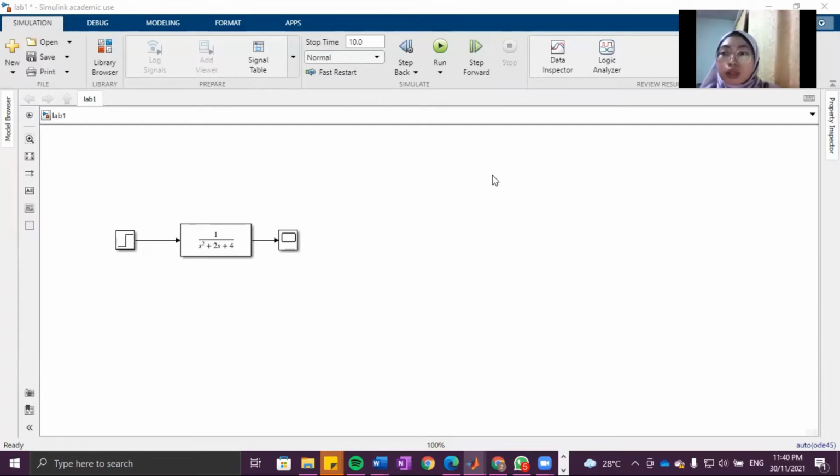So how is the data acquired? We can design a simple transfer function and get the data. The block diagram needed for this part 1 only needs 3 blocks. The first is step, transfer function, and scope. The step function generates the signal, and the scope displays the signal.